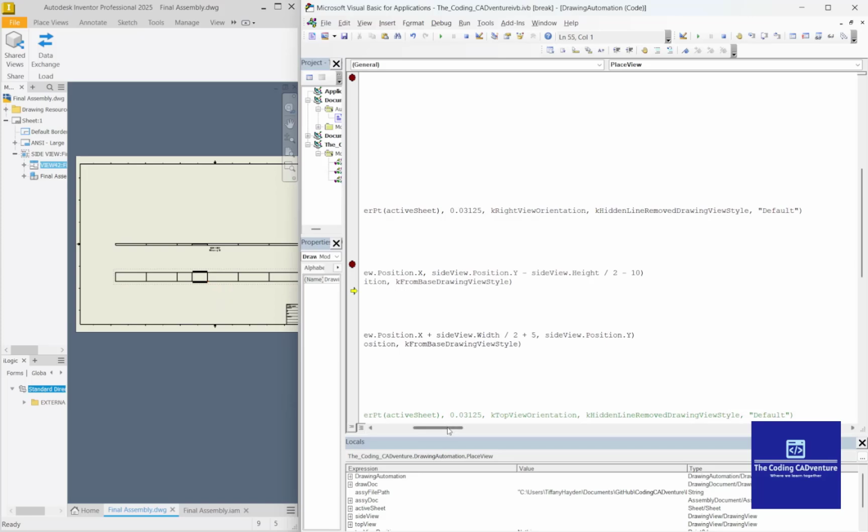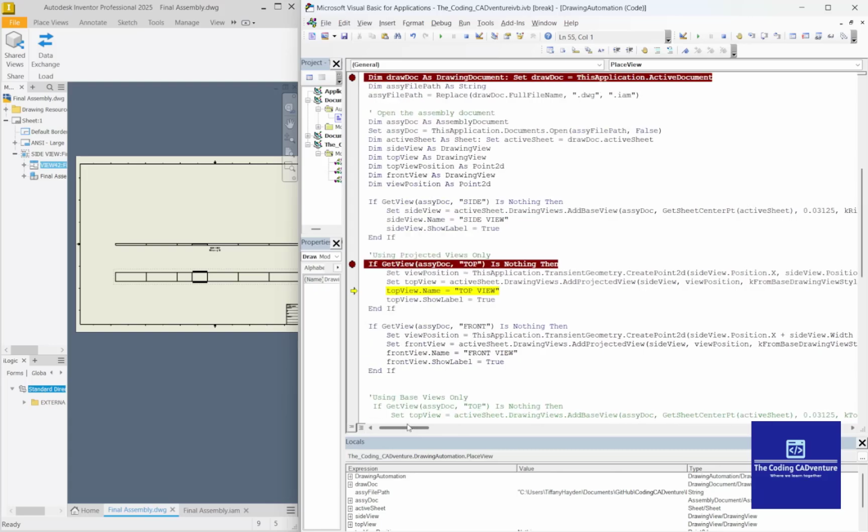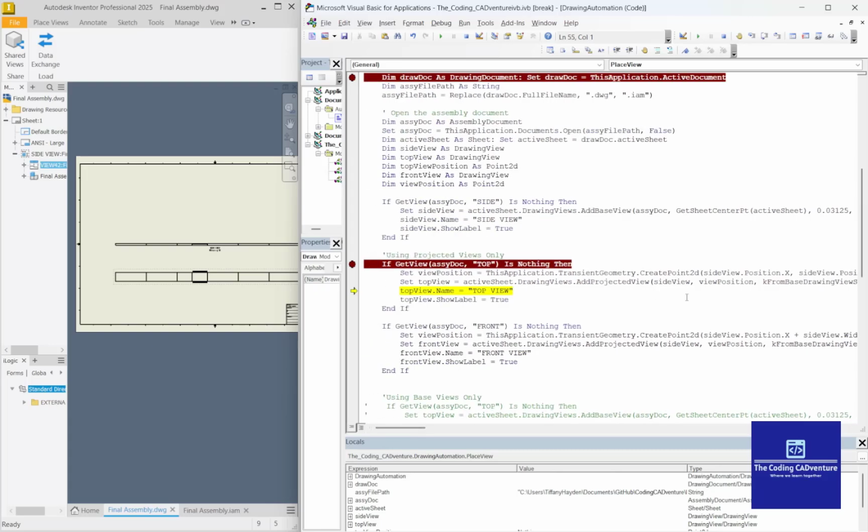It's going to make the assumption, because you said base drawing view, that because you went down here, this view is going to be a bottom view and not a top view. And that is the key, because it can add some confusion when you are doing different types of views and you're using a base view.